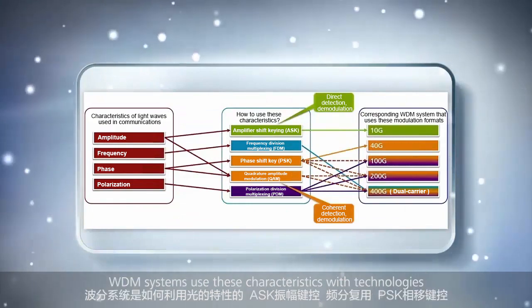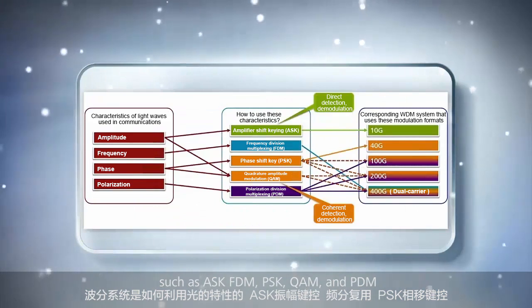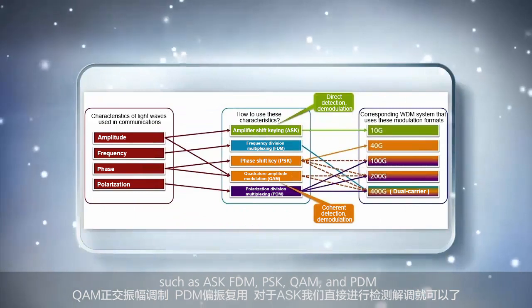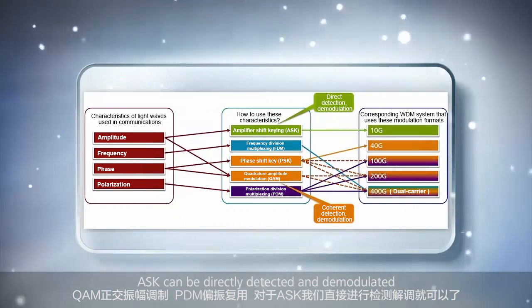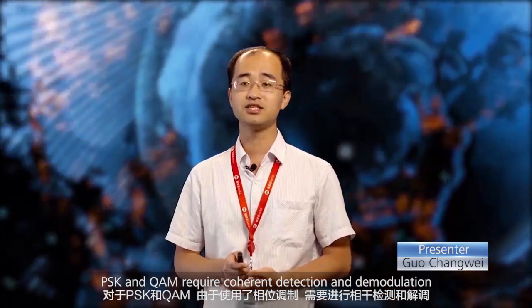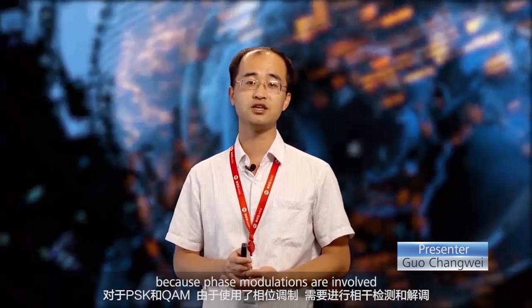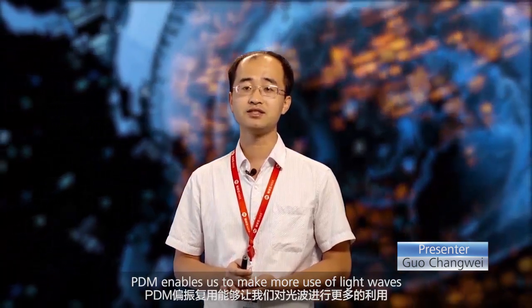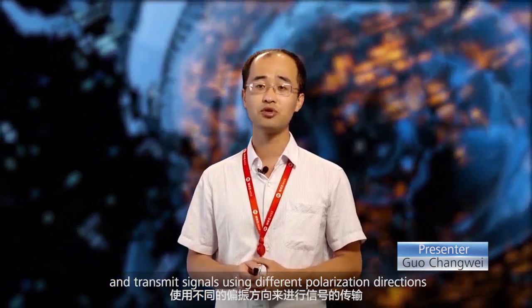WDM systems use these characteristics with technologies such as ASK, FDM, PSK, QAM, and PDM. ASK can be directly detected and demodulated. PSK and QAM require coherent detection and demodulation because phase modulations are involved. PDM enables us to make more use of light waves and transmit signals using different polarization directions.